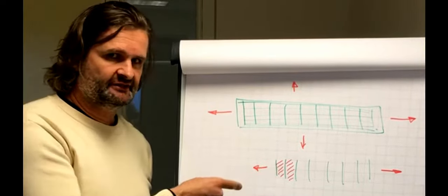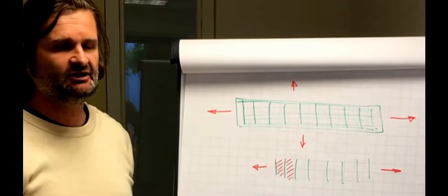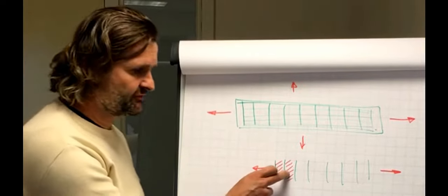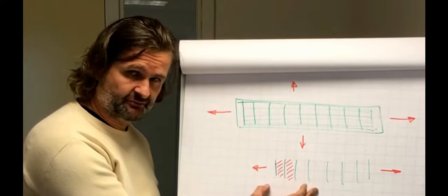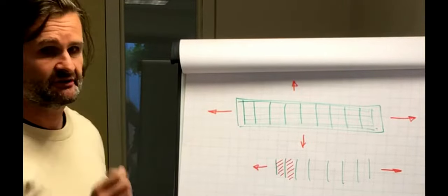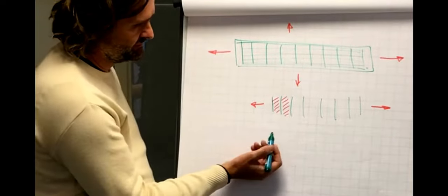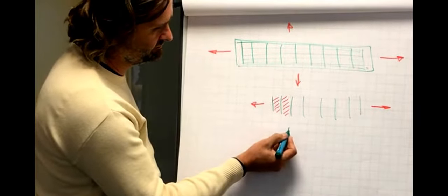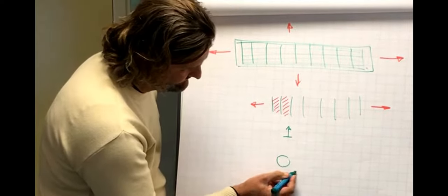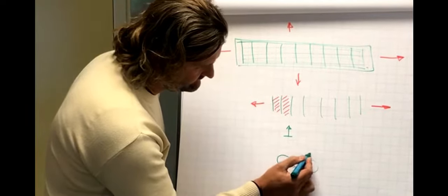This is the cause of it, and what we can do to mitigate this a little bit is to get resin that is a little bit more flexible. So if the resin is more flexible, we can allow for more deformation in this direction without failure. But that's only very limited, because if I look at this layer from this view, and I look at the fibers, actually the fibers look like this.